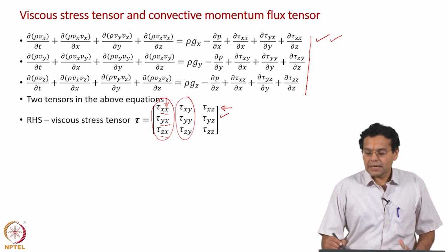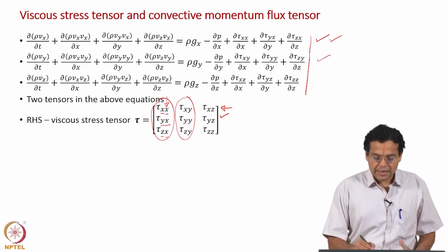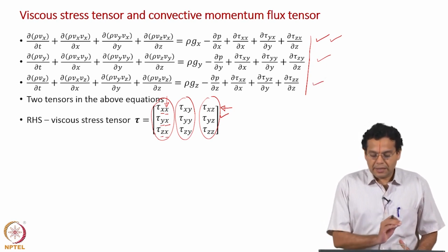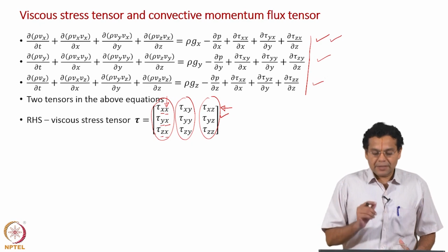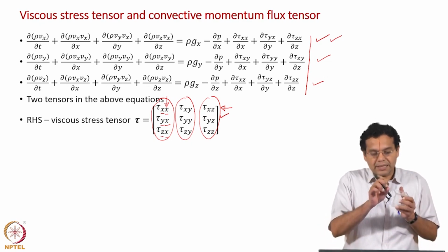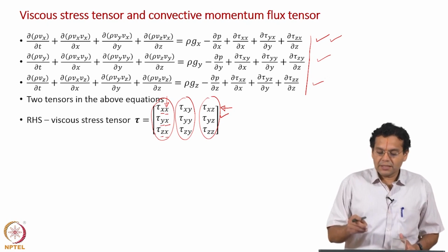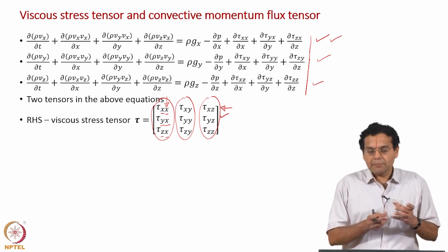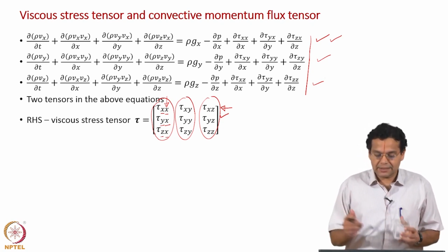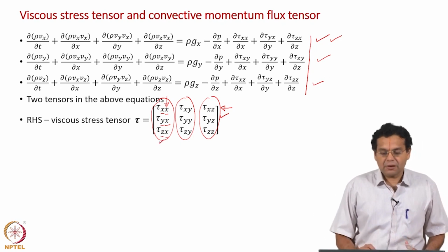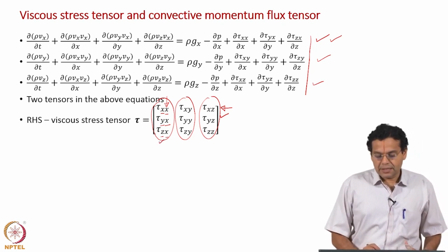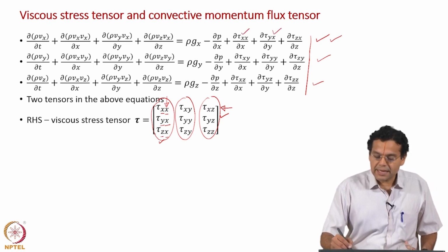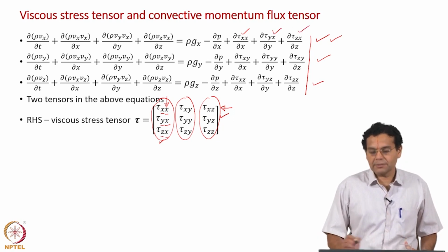stress tensor components are appearing in the y momentum balance equation, and these 3 are appearing in the z momentum balance equation. Okay. So, let me repeat, the significance of each row is that they are components of a stress vector acting on a particular plane, but what we need is components of 3 different stress vectors acting on 3 different planes, but all the components should be directed along the x axis. They are all appearing in the first column, and that is why the stress tensor components appearing in the first column appear in the x direction momentum balance, similarly y direction, similarly z direction.